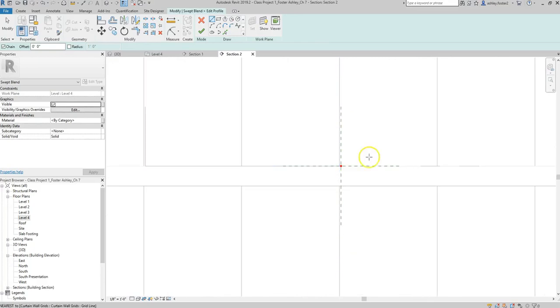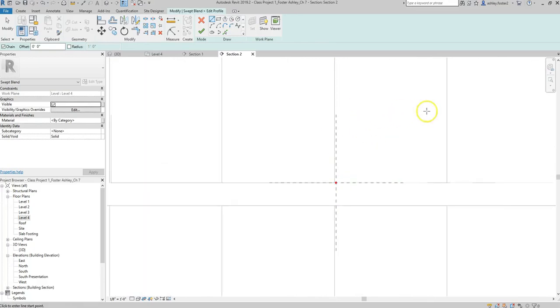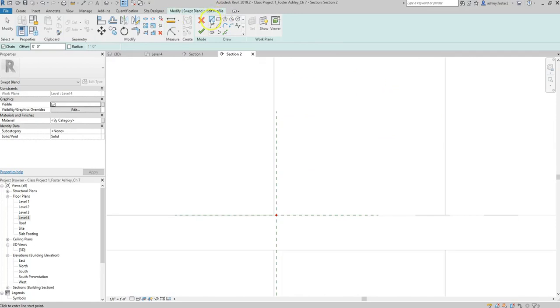And then we're going to zoom in to the reference planes and that red dot, and we're going to do something similar, but this time create a stool type shape. So we'll go up maybe 1.5 feet with the line tool, and then choose the spline tool, just that one there.